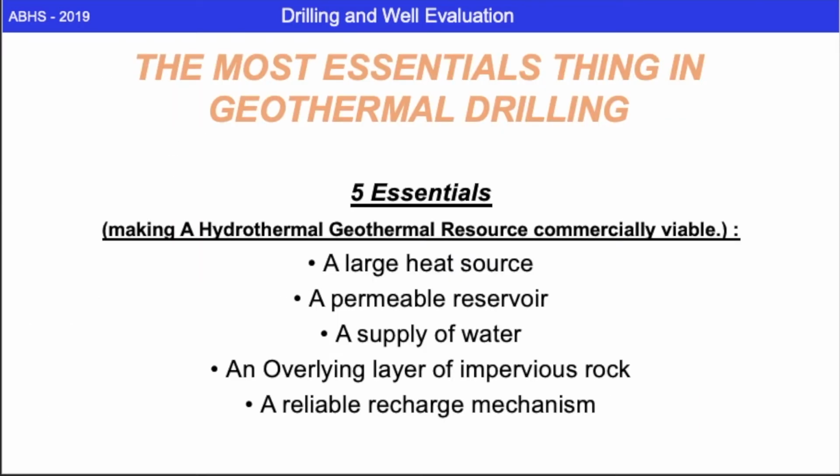The purpose of drilling in a geothermal well is to determine where the heat source is, the permeable reservoir, the supply of water, the overlaying of impervious rock, and also the reliable recharge mechanism. This is in line with the purpose of making a conceptual model. Therefore, drilling is actually just a confirmation of this conceptual model that we have built prior to the drilling process.